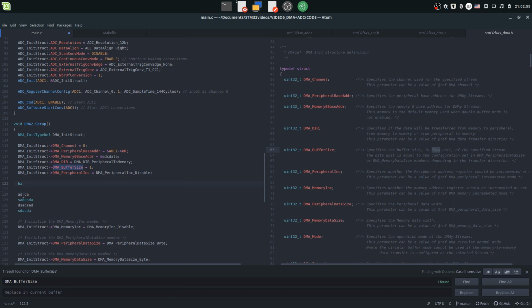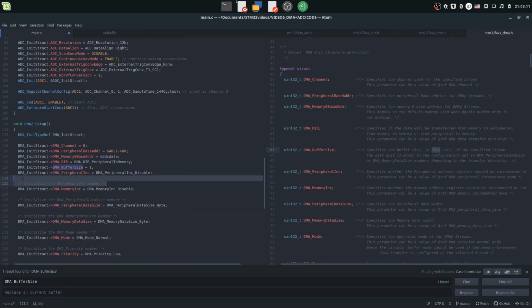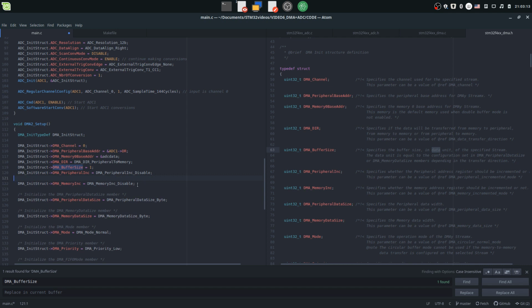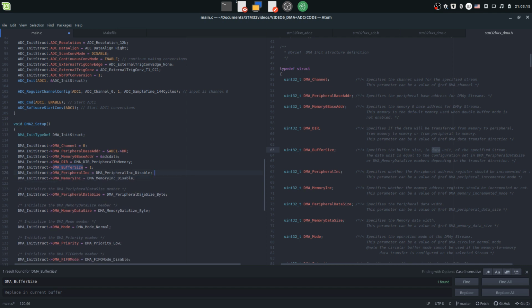And if you want to copy data inside here and then inside here and then inside here, we want to enable the memory incrementing function, so it does that automatically for us, so we don't have to do that ourselves. So this is useful when using an array. But now we're just using a single variable, so this can also be left disabled, but we will enable this later.